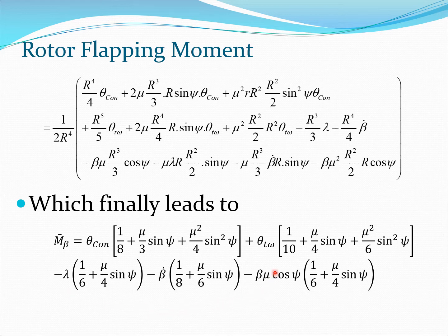Now the interesting thing here is the presence of these motion dependent forces. So actually you have motion terms in the right hand side of this equation here, and these terms cause a lot of complexity. Actually what you should do is take them to the left hand side of the equation before you solve the equation, or you are going to encounter significant problems in their solution.